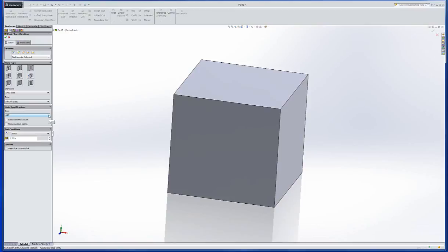Here we've got the actual size of the hole. A 97, if we hit that and we showed the decimal value, we can see that it's just a little under 6 thousandths of an inch diameter. So those are rather small. Okay, it might be better if we turn that show decimal off while we're just looking for it. But let's say I wanted to just drill a 1/2 inch hole. Maybe I'd go in here and go to fractions, and then go down and find 1/2 inch. Drill down through there. There's my 1/2 inch. And again, you could show that decimal if you want.